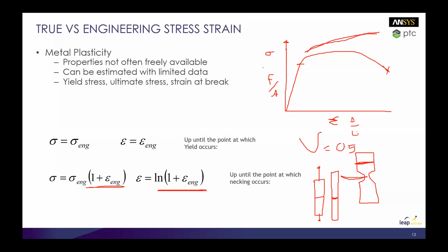Okay, I've got a question about how we get the static and dynamic coefficient of friction for different materials in dynamic simulation. Probably from the literature you can find static and dynamic friction coefficients. We can just input a scale factor between the two. There are more elaborate things you can do, like changing the friction coefficient based on sliding distance, for example, but that's more advanced. There is some material in the help that will show you how to do that.